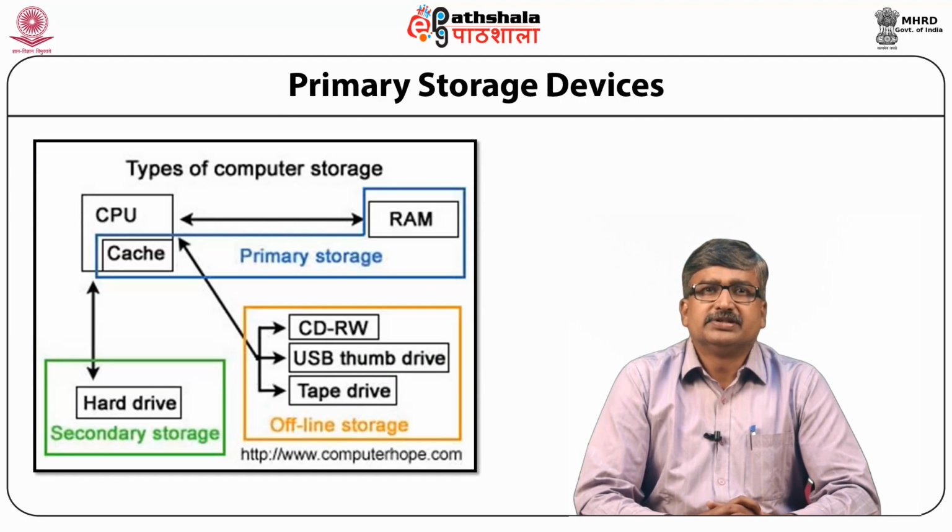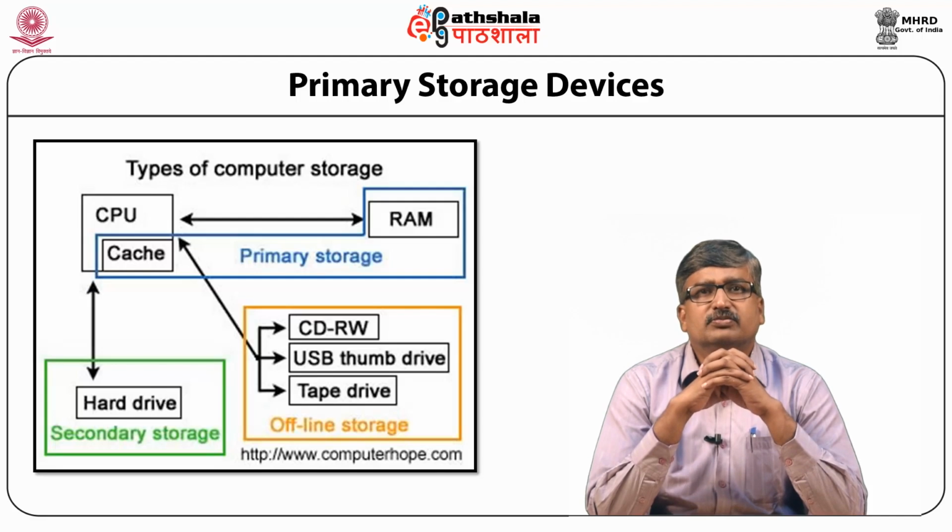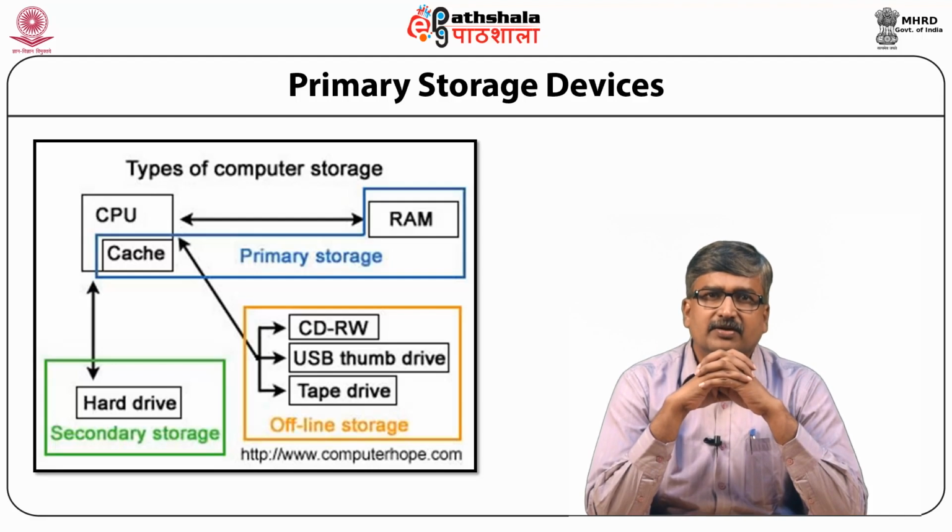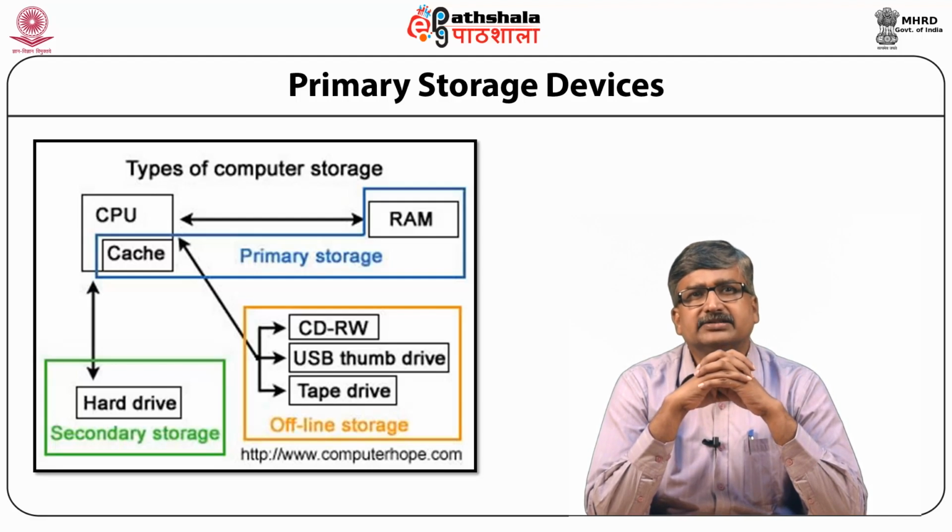Magnetic materials are used in various day-to-day applications such as in motors, generators, electromagnets, low and high frequency transformers, magnetic field screening, permanent magnets, loudspeakers, analog and digital data storage, telecommunication, etc. Some of the widely used permanent magnetic materials are magnetite, magnetic carbon steel, alnico magnet, which is alloys based on aluminum, cobalt and nickel, cobalt platinum magnet, hard ferrite magnets, samarium cobalt, neodymium iron boron magnets, and samarium iron nitride.